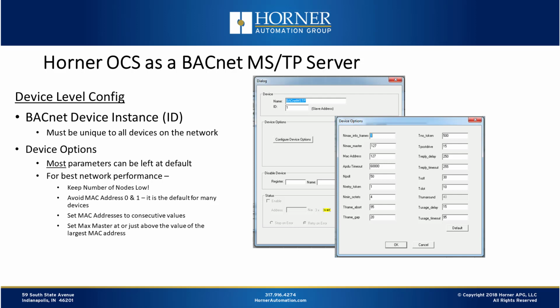And then you've got a whole slew of device options for configuration there. Those are different parameters that can be used for adjusting the token passing that is happening with BACnet MSTP. Token passing networks used to be extremely common, and they've become a whole lot less common over the last several years.